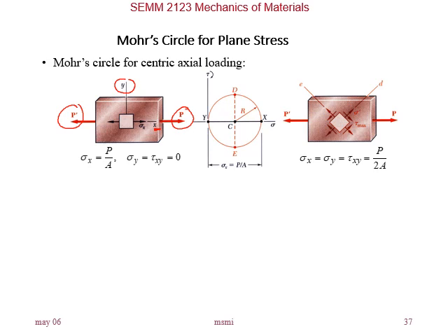So when we plot the Mohr circle, what we get is sigma x is that, and sigma y is 0. So sigma y is right on the origin of the graph, okay, where the two axes intersect. So that is the 0 point. So we only have x and y.